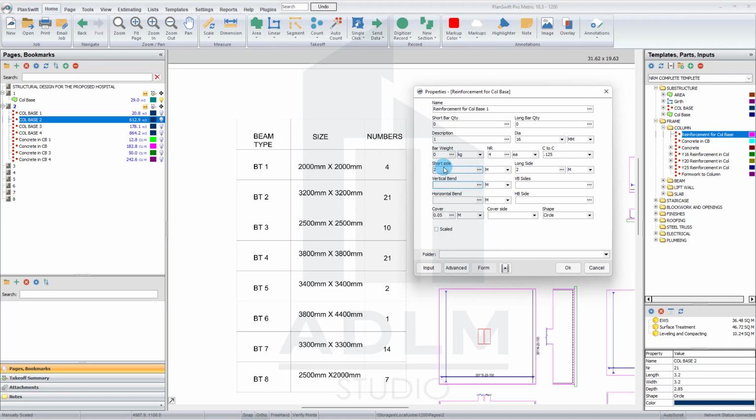So for the bend now, we know we have our thickness as 0.8. Then remove the cover and all, that's 0.7. Now you can just write 0.7 plus the extra bend, let's say 0.15 extra. Then we have it on 2 sides, the 2 sides of the column base. The horizontal is the same thing, since it's similar, plus 0.15.